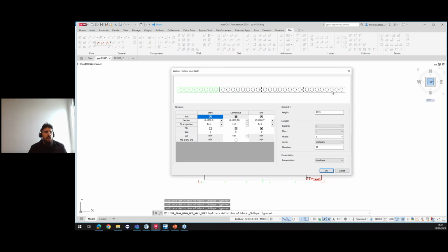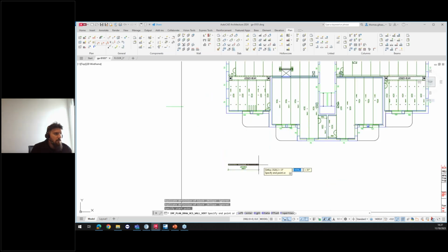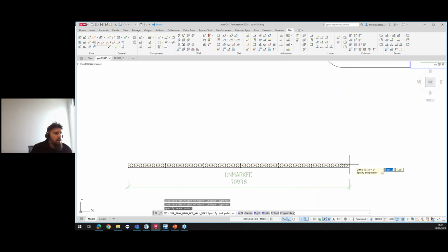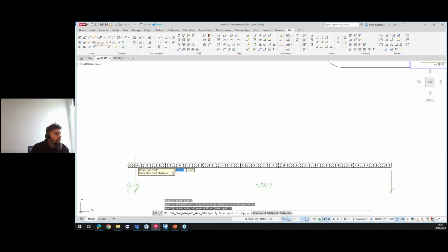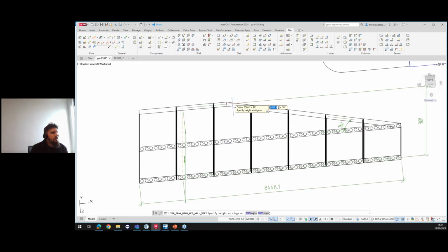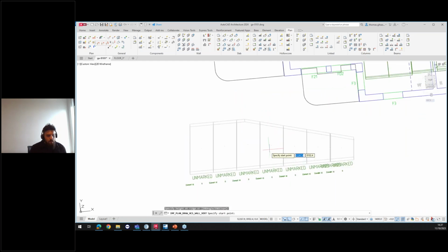This is about external factory walls, external walls for buildings or countries with no real seismic problems. And you can see just a small example of how it looks. You go like that, and then it creates Hollowcores, and then you can just decide where to finish and where to stop. If you want to have a cut Hollowcore or whatever, I'll stop here, and then you can add the ridge, and that will go from here to here, and then I will just move it so you can see that I can actually have a ridge of like 32.4, that is 33 degrees. These are my Hollowcores.